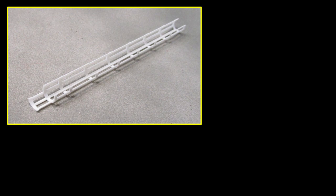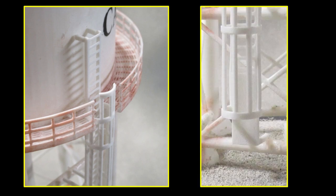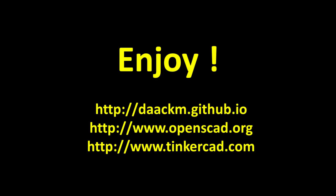For the cage on my water tower, I modified the OpenSCAD file to add an additional ring a few millimeters below the top and remove several of the vertical splines between the new ring and the top. I did this so I could extend the cage to connect with the catwalk around my water tower. I also added an access door for security at the bottom of the ladder. While I made these modifications in OpenSCAD, they also could be accomplished in Tinkercad or another CAD package.